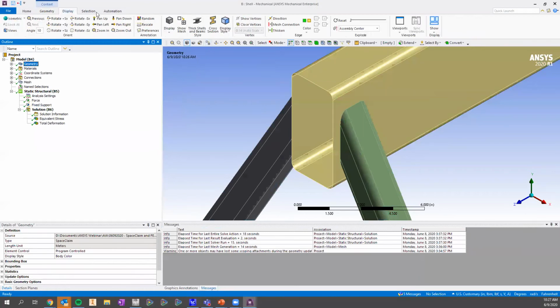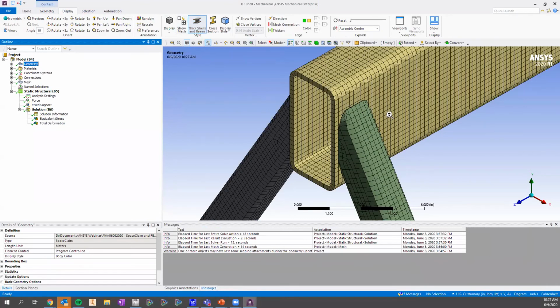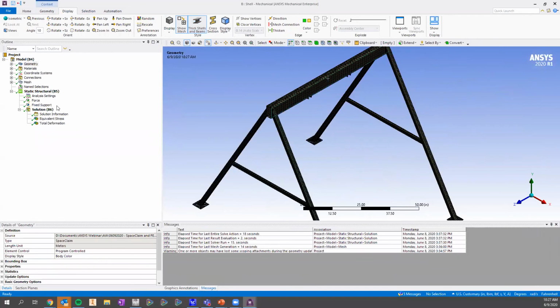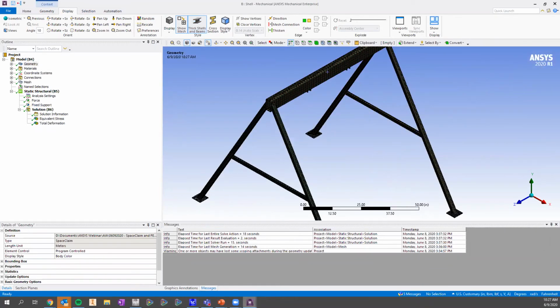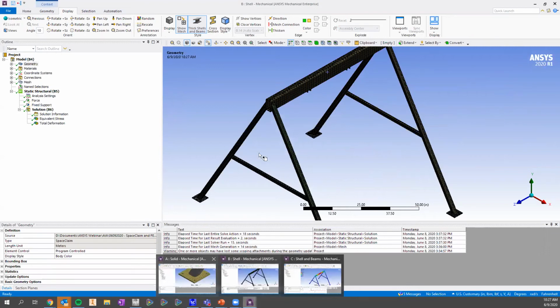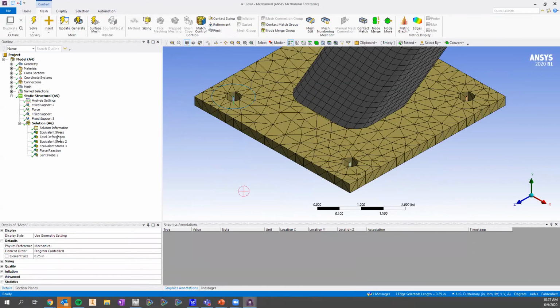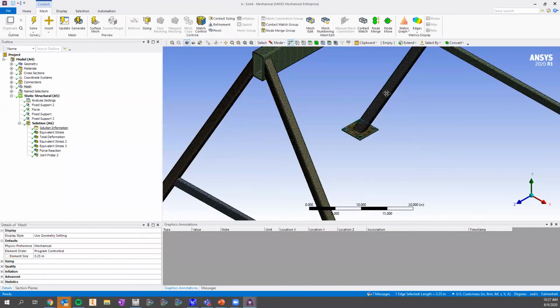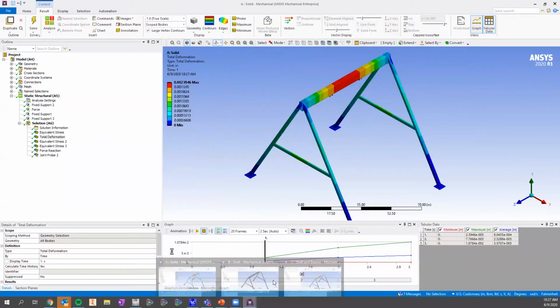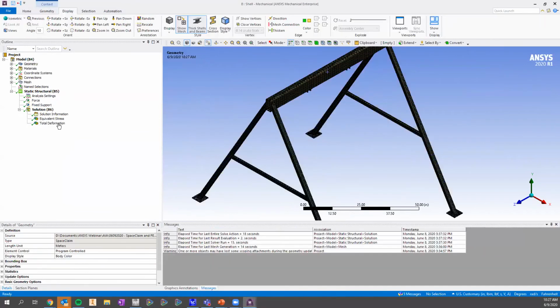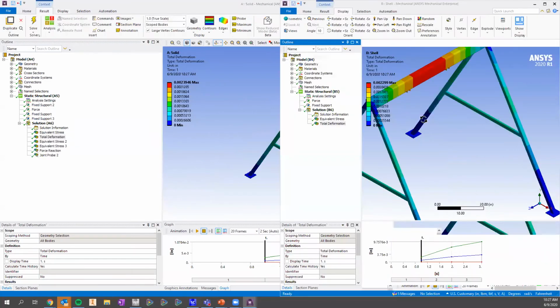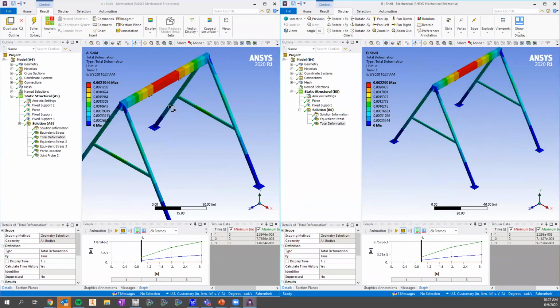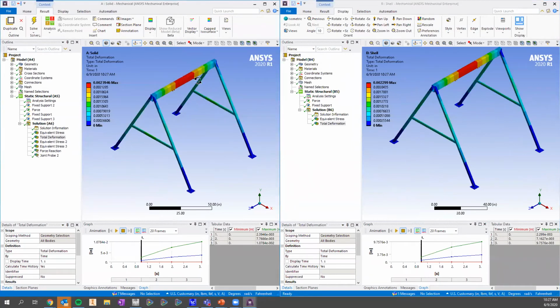Let me display over here the thickness of the shells, of the elements. And I did the same analysis I did with the solid bodies on the shells. So let's get a little preview of that. I'm going to go over to the shell body, click on deformation, and try putting these simulations side by side. And you can see the deflection, guys.